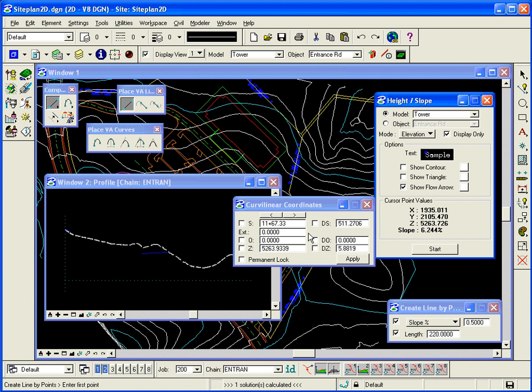And then I'll do the other side, place line. This time I'll just tentative to the end point of that blue line, and I'll go down for 260 feet. So I'm going to lock in a length of 260. And that carries me beyond the parking lot on the other side of the building.